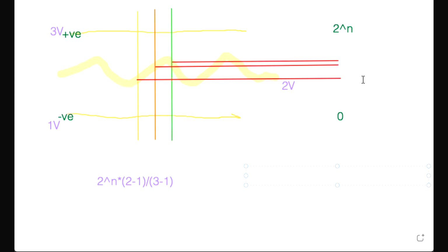Yep. All right. And to make life simple, in question 1, I said I want you to do a circuit, because remember, you could do an infinite number of circuits to connect the resistance to the PIC. So that's why in question 1, I said give me a circuit which, when you hook it up, gives a proportional voltage, a voltage that changes proportionally with the resistance.